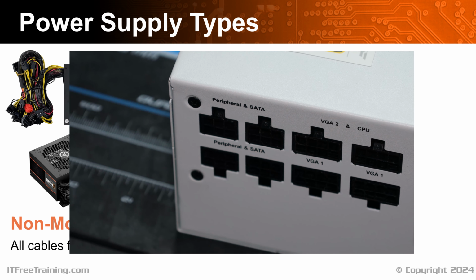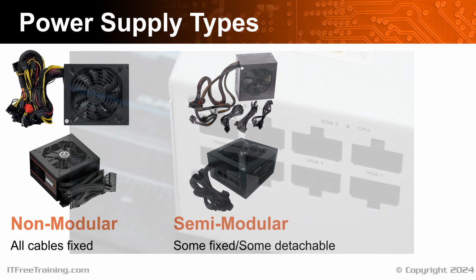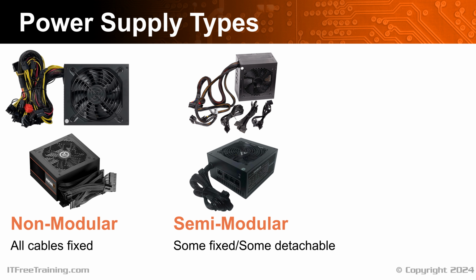The power supply does not make use of any standard for the keying of the cables. Thus, different cables from different power supplies may plug into the power supply. However, the wires in the cable may be different. Be careful. If the cables are wired differently, this can cause the wrong voltages to go through the wires and damage components. Even power supplies from the same manufacturer may be wired differently.